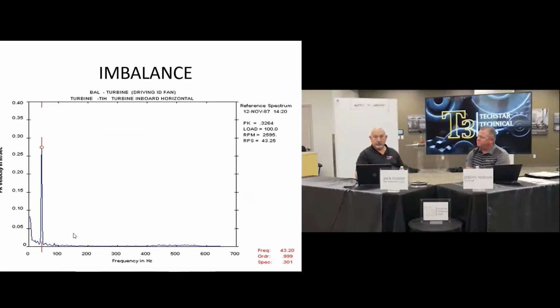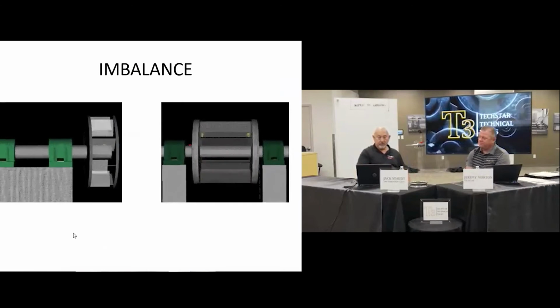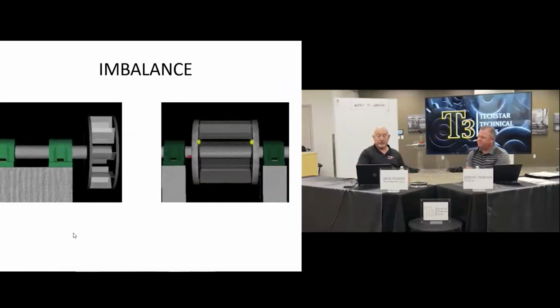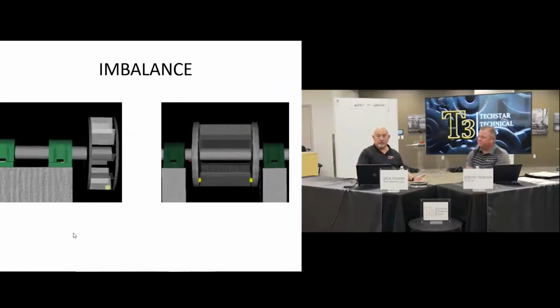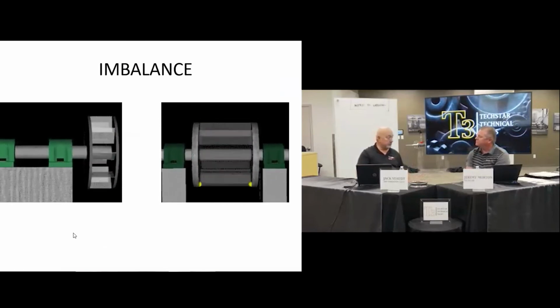And again, here we're looking at data from November 1987. 1X was the same as it is, you know. Didn't change, did it? That's right. So we have pure 1X frequency, a good indication we have unbalance. Kind of showing the difference between overhung rotor unbalance and center hung rotor. Okay.